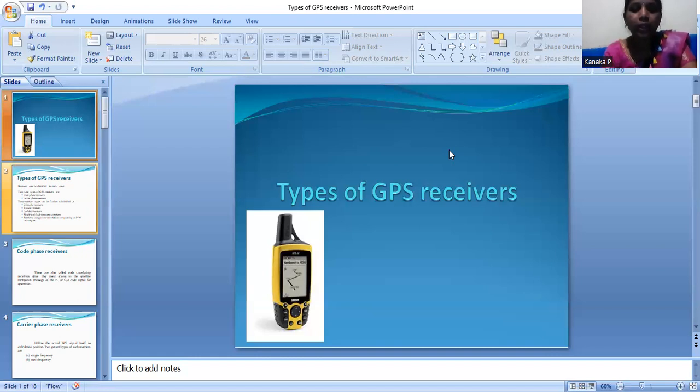Simplified orbit determination is a developed method that uses pure geometric and pure dynamic methods. This method uses two consecutive approaches or two-line elements obtained over a period to create the navigation solutions. Next one is orbit representation. Orbit representation consists of semi-major axis, eccentricity, inclination, longitude of ascending node, argument of perigee, and mean anomaly. So these are the orbit components.